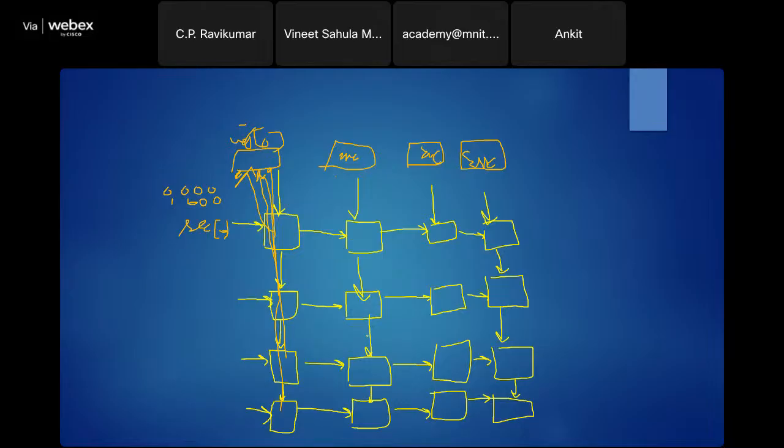We are not really doing it in two steps. We are sort of comparing, and then the result is a combination. As soon as you give the user guesses and these secret values, all these comparators will act together, and the outputs will become available here. Based on this algorithm that I just mentioned, 0000 means minus, 1000 means bull, and so on, it will immediately produce the feedback string. So it's not a sequential circuit in the sense that we are not doing it one after the other. It's a combinational circuit.